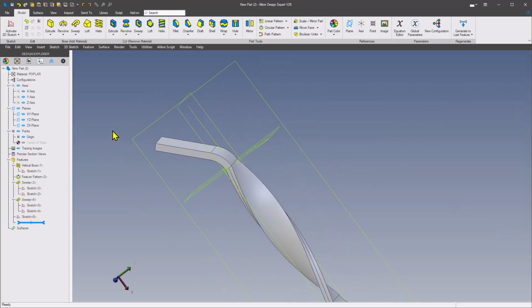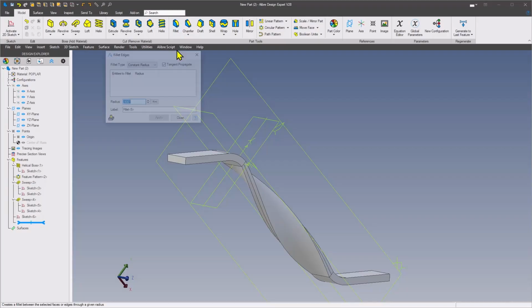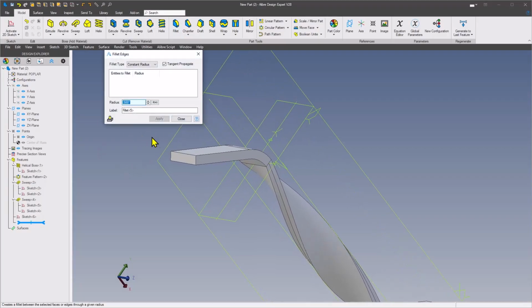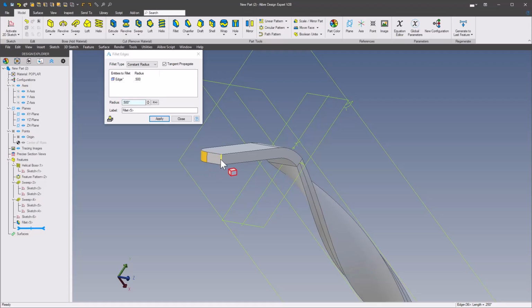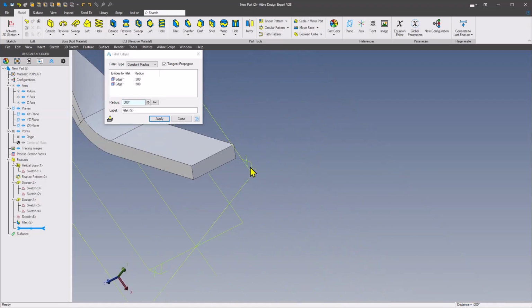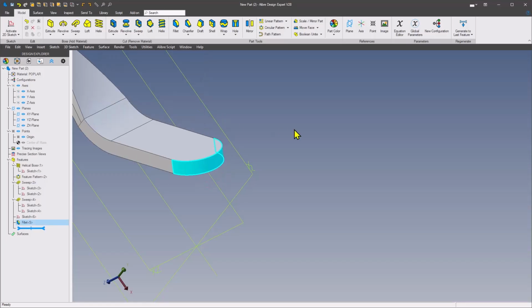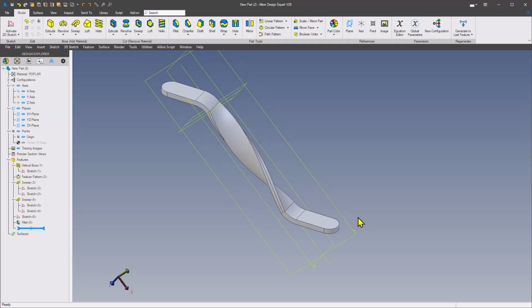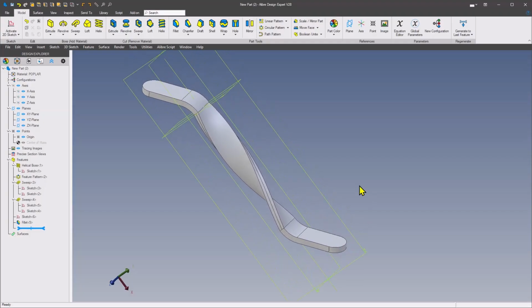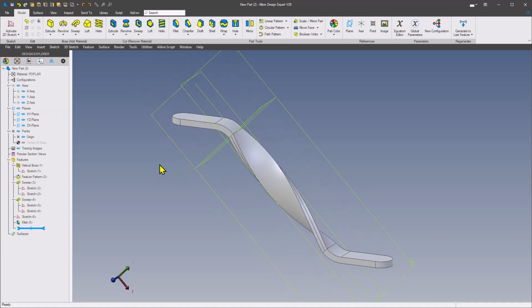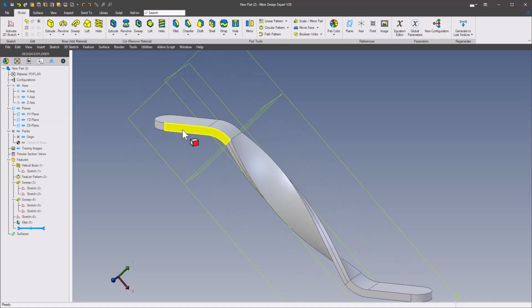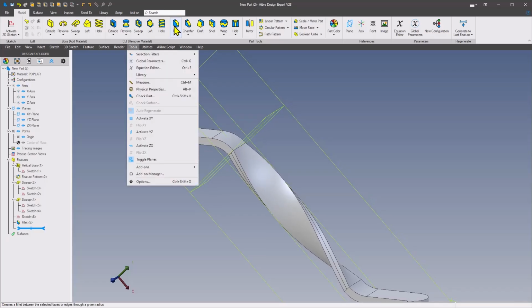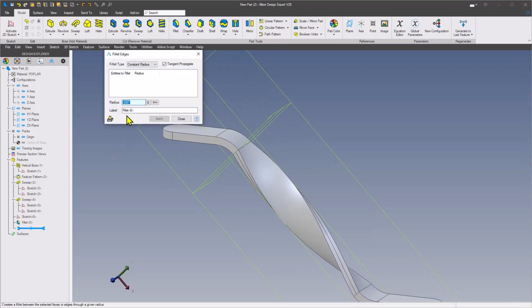Okay, there's a couple other things now. Say you want to round off the ends here, we'll just go in here. We say we're 1 inch wide, so we'll grab these edges here, and we're rounding that to a full radius end at a 1/2 inch. So now you've got somewhere you can put a hole through here that's going to be in the center of this bend, or center of the radius end. And if you wanted to finish it off with taking the edges off of there with a fillet on the edge, 0.03, say 30 thousandths on there.